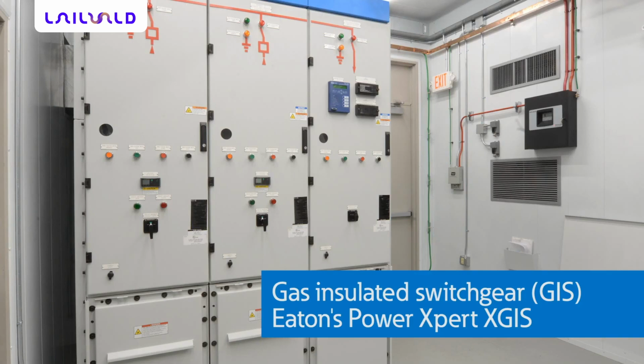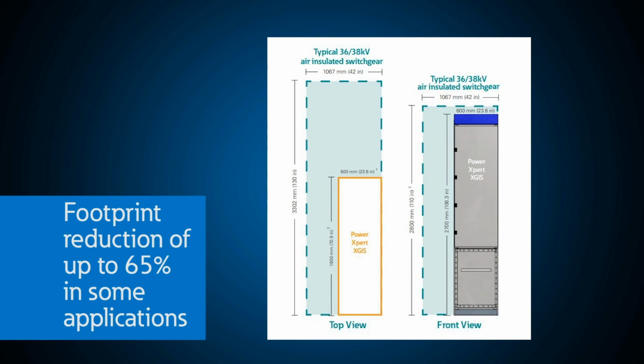Gas insulated switchgear, GIS, has sealed enclosures filled with an insulating gas, SF6, or an alternative gas. The gas-filled sealed enclosure facilitates a footprint reduction of up to 65% in some applications. The use of gas as an insulating medium, when compared to similar air-insulated switchgear, allows for the distance between the interrupting components to be reduced. The IEEE organization standard is C37.20.9 for GIS, and the IEC organization standard is 62271 for metal enclosed switchgear and control gear, which include GIS.